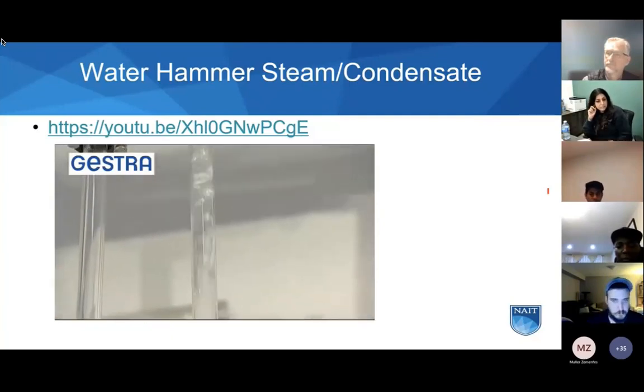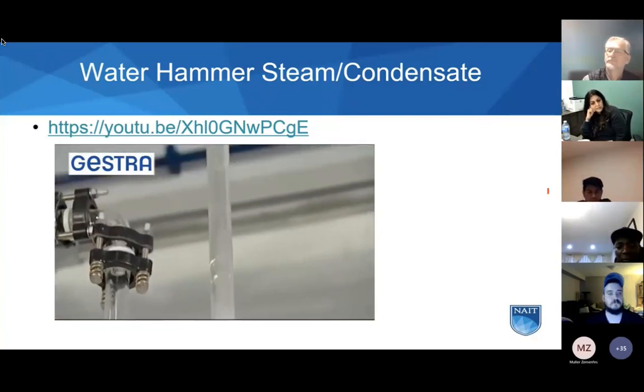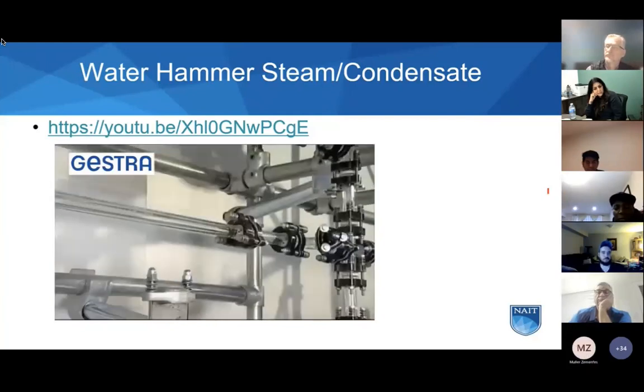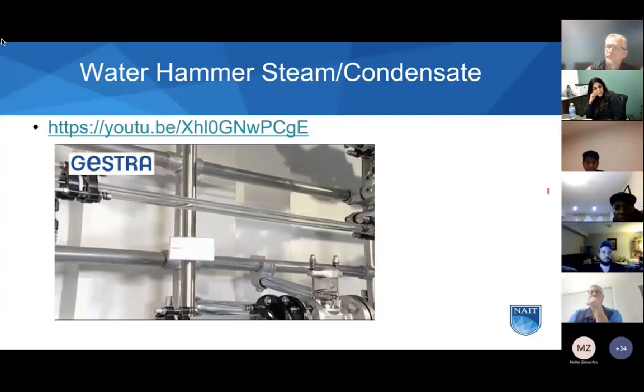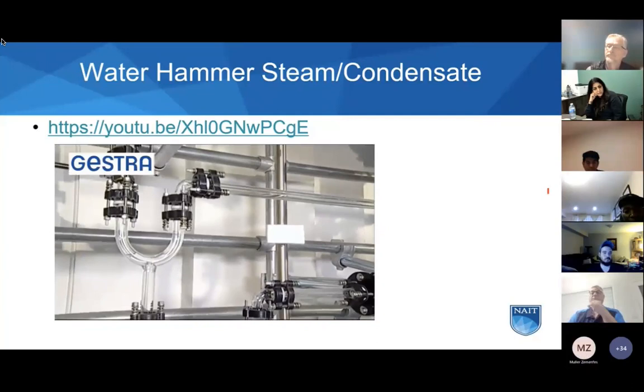Once the entire body of water has warmed up to boiling point, the steam bubbles condense at only a very slow rate. There is then no longer any danger of water hammer. The experiment is repeated a second time. This time, however, this part of the horizontal tube is arranged to have a slight drop towards a siphon.